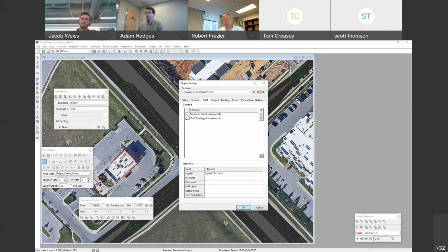Maybe the example is you are doing some type of traffic analysis and you add a development, a distribution center, and you want to do trucks in an OD matrix, but your background traffic is based on turning movements. I need to find the answer to that question. I'm sorry, I don't know it right offhand, but I really think it's good practice to do an OD matrix whenever you can develop one, because then your application of that becomes a lot broader. But we've made it very simple to enter intersection turning movement counts as well.